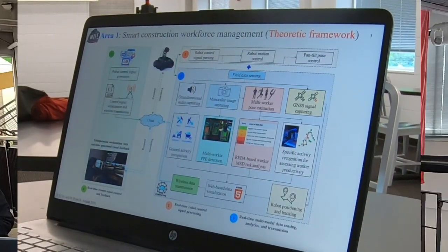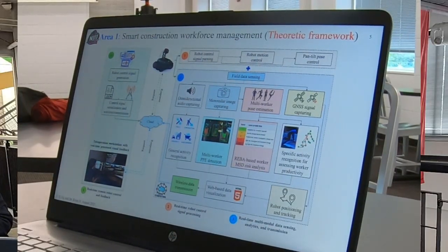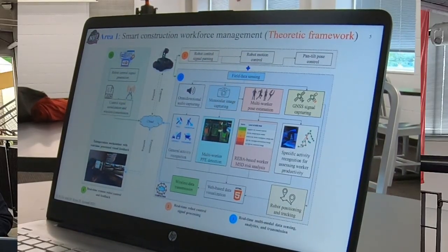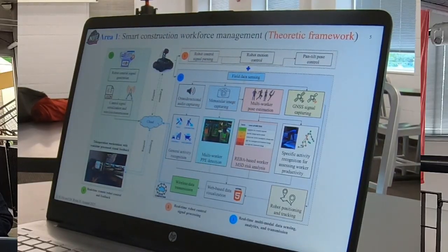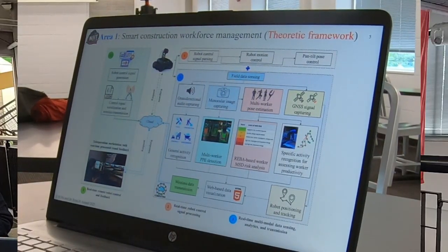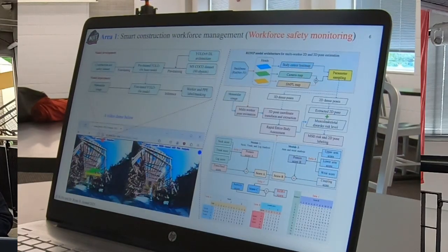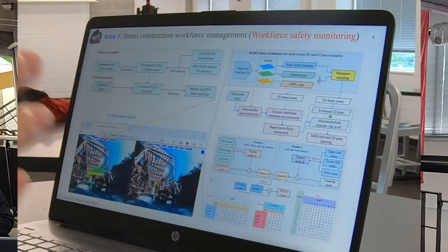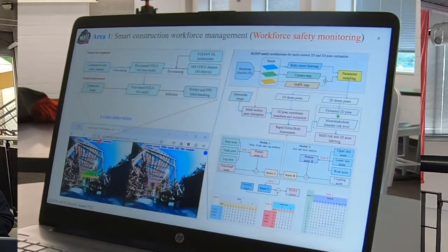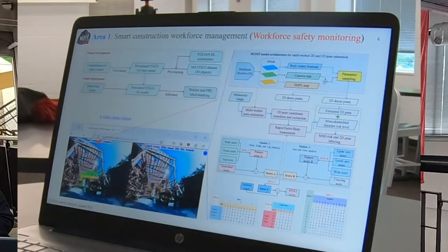And then on the left-hand side is a regular USB camera that is installed on a pan-tilt system. Even when we drive the robot, if the camera is fixed and we want to turn the camera to different angles, we have to drive the robot to do that. That may cause some inconvenience. So this pan-tilt system allows the teleoperator to just click a button, turn left, and turn the camera, not the robot. Yeah, so to enable more maneuverability.